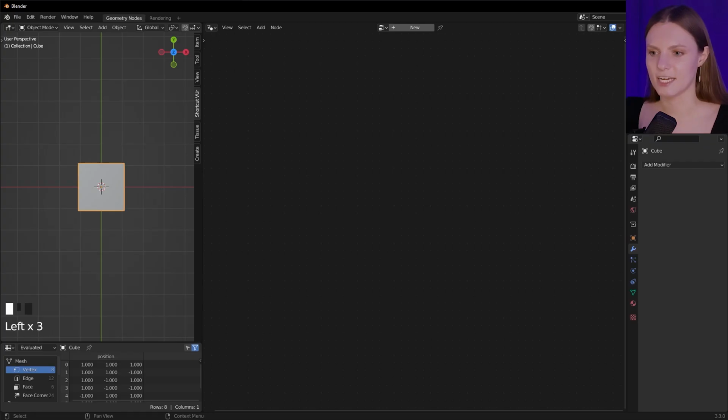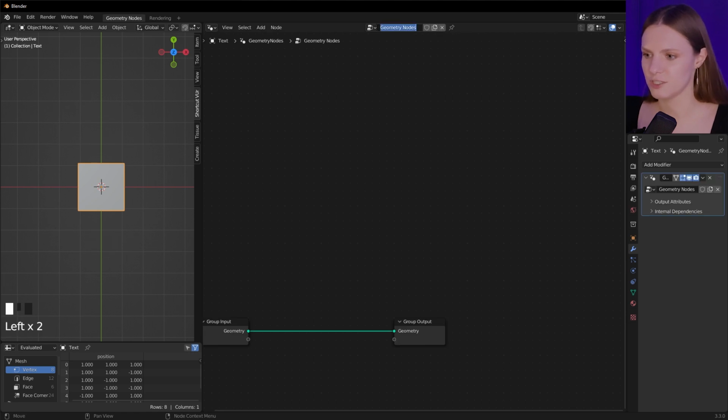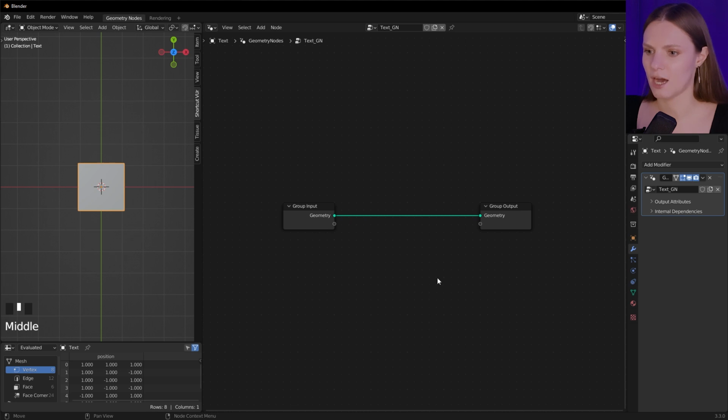The advantage of using geometry nodes is that in fact we create a template and therefore can easily make changes in the future. Once you need to do more, then always do less. Moreover, using input node, you can change all parameters in one place. Let's start by renaming the cube to text. Let's add geometry nodes and rename them. By default, we have input and output nodes.